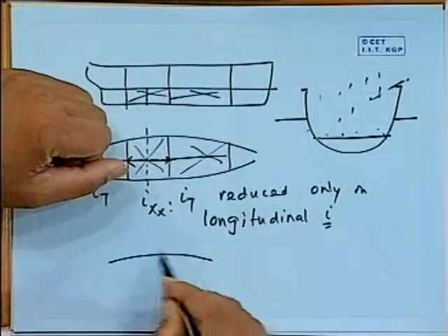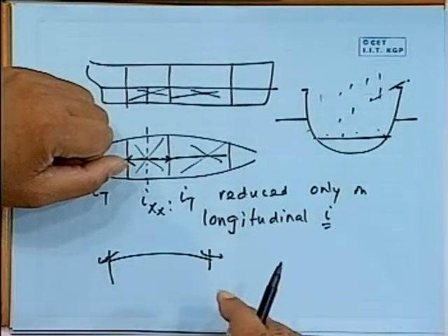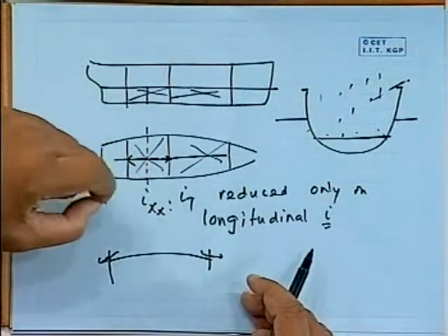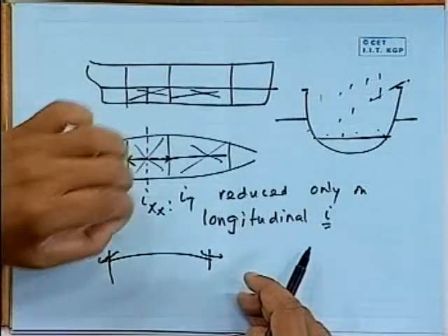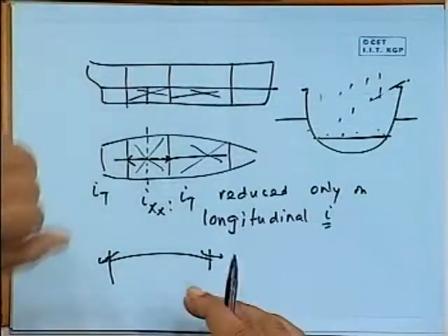Of course, you have a larger freeboard because of safety, since water cannot go in. You cannot have this more than a certain angle. Otherwise, liquid will go in and it cannot come out. That is why you have to have a large freeboard. But in addition to that, from our point of view right now, on the free surface, rainwater must be drained, but you cannot make a hole here like in a deck. So you have to have a pump. Similarly, on the deck, you have to have rainwater draining holes. Very essential, because rainwater accumulates, especially for small vessels, and might cause some kind of free surface effect.